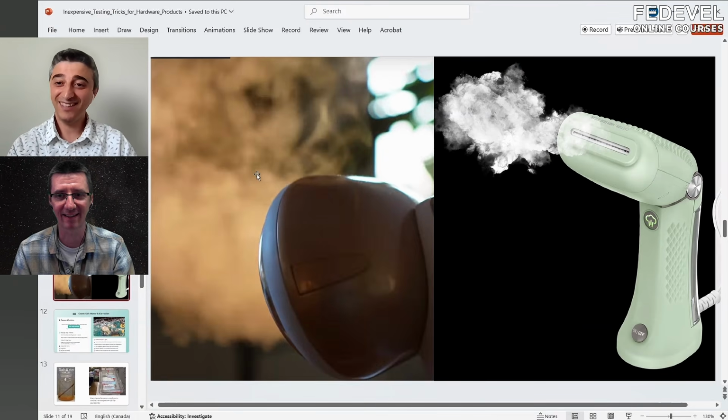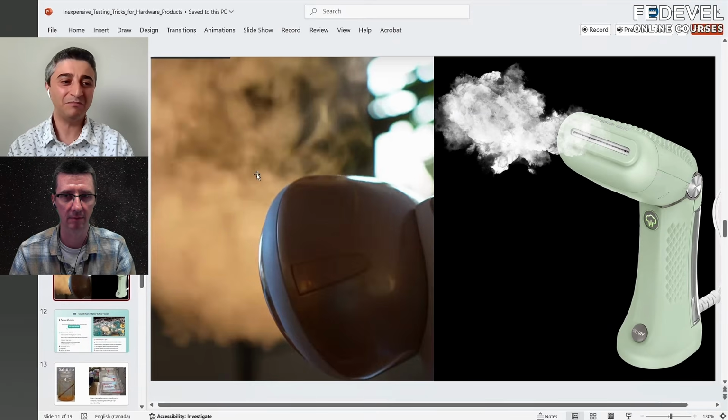Yeah, that's exactly what I was thinking about. It's very hot, maybe beyond 50 degrees Celsius, so be careful when you're doing the test. But I find it very useful, especially if I have a design that has a real-time clock that might drift with the humidity. So this is the way you can just point it closely, let the humidity settle, and see if that real-time clock is drifting and how much that drift is.